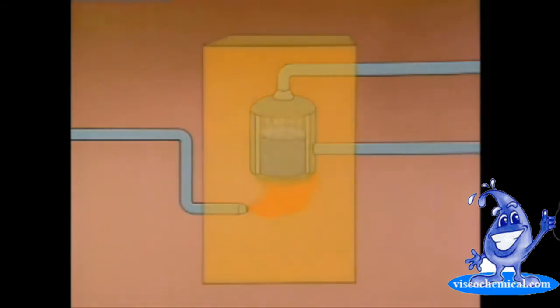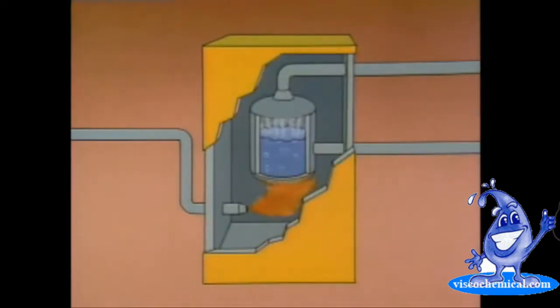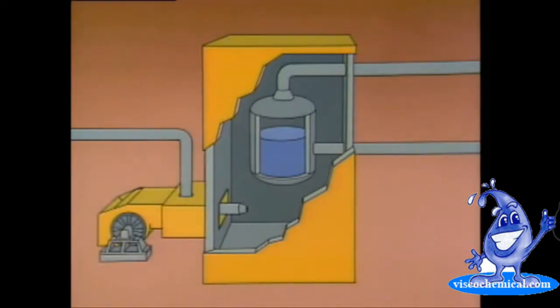This boiler can be modified further to make it more efficient. By adding an insulated casing, we can minimize the heat loss, but this creates another problem. The flame goes out because the casing cuts off the source of air. To correct this, we'll add a fan to supply air to the boiler and an outlet to remove combustion gases.